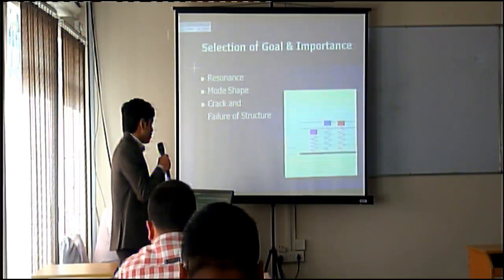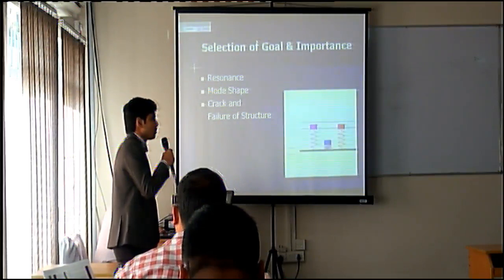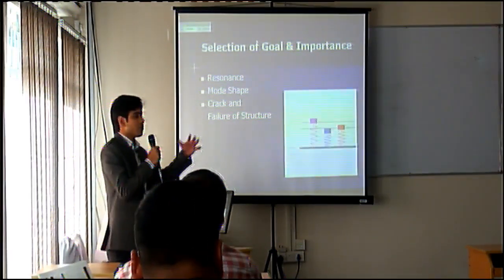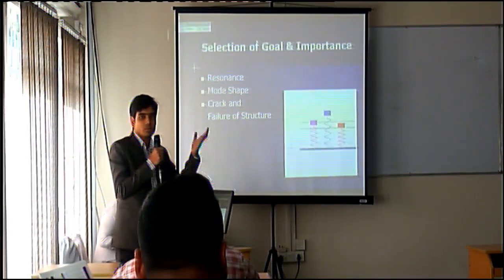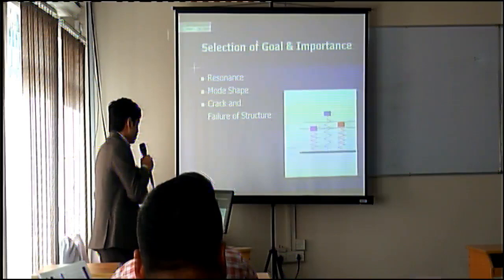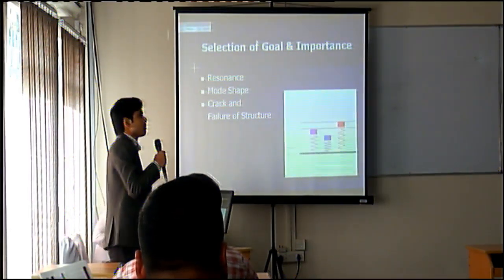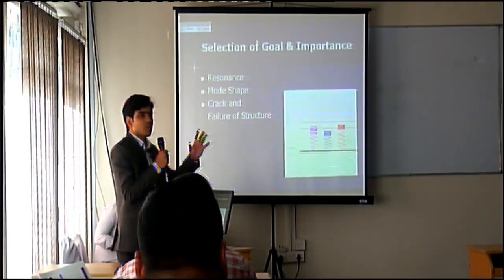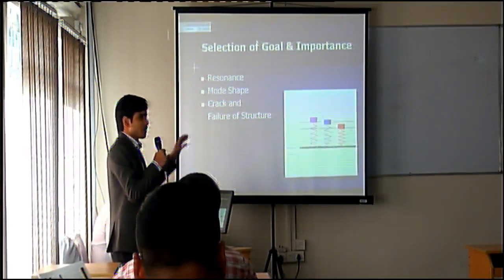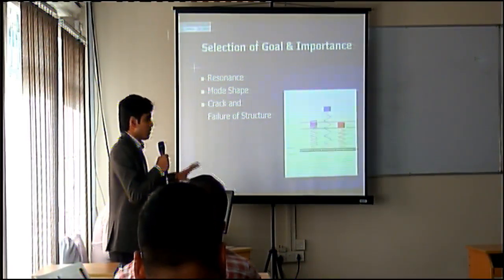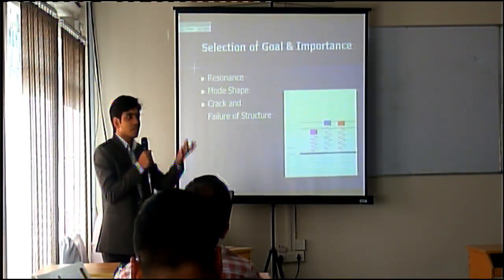So the importance of this study focuses on the things of resonance. We know that when the applied load frequency matches with the natural frequency, the structure may vibrate with higher amplitude, which may cause failure. So it depends on mode shape, and I have taken this study to see how the frequency varies if a crack is present. It reduces when the crack is present in the structure, that is, uncracked beam and cracked beam frequency is not the same. When the crack is present, the frequency reduces.